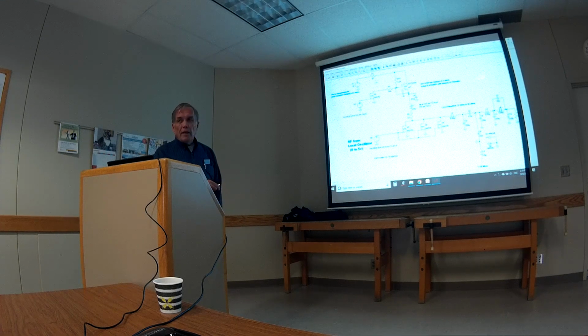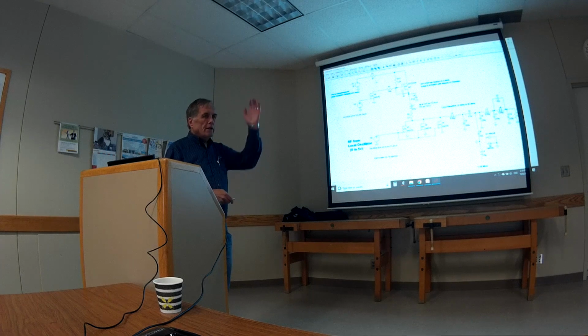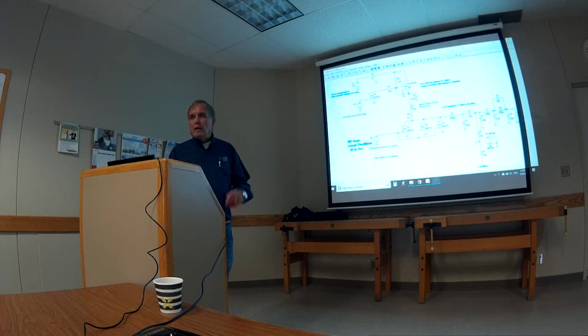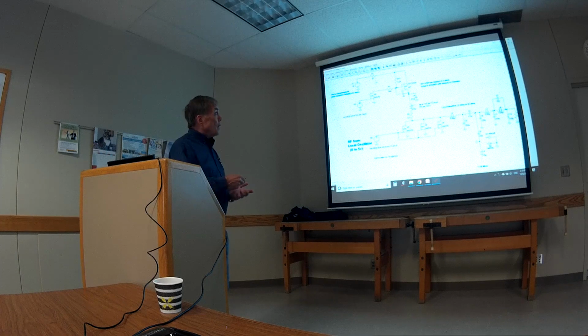Now, typically in the keying circuit of these kinds of things, we use a PNP or a P-channel MOSFET instead of an NPN or N-channel MOSFET because the current flow is a little better. You can see that the particular one I have here, the SI7137, is there because I had a model for it. I don't have the model for the one I really want to use. The spec on this one says that when this is a low instead of a high like it is on the other one, it gives about 2 ohms of resistance across here, which is pretty high for this kind of circuit.